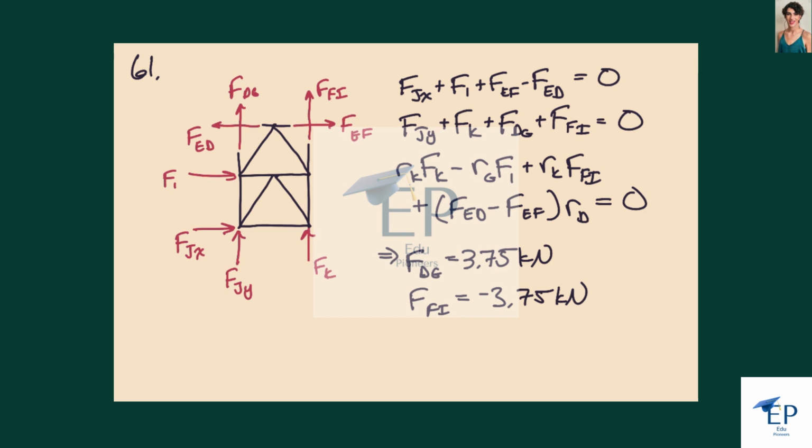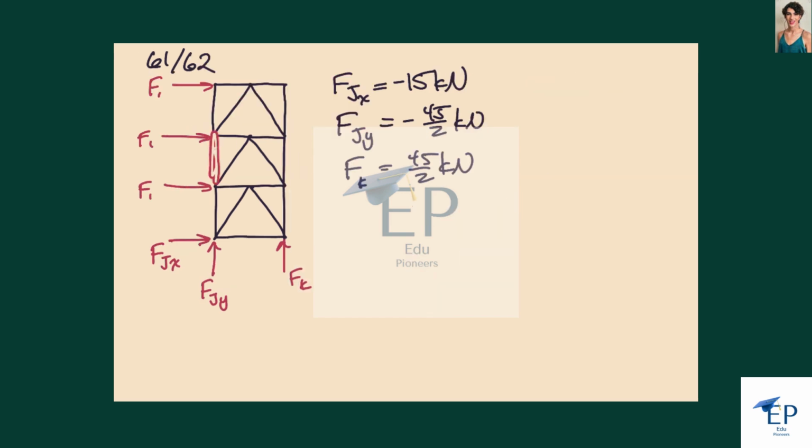And if we compare to the previous one, up higher on the structure, the forces in these members are lower than they are here, because these ones have to offset the moments created by all of these wind loads. Assume wind loads on this building. So as we go down, this one would have lower forces, and then the middle, and then the greater. So we get greater forces in each member as we go down from the top of the building.